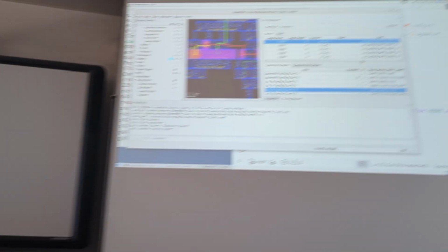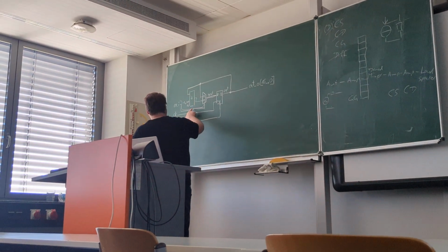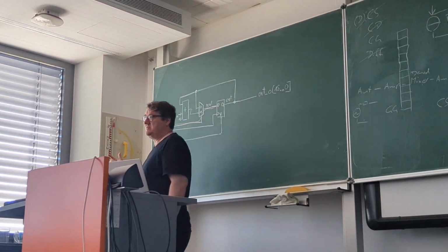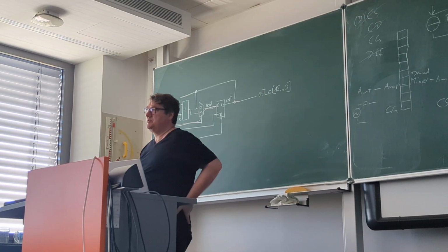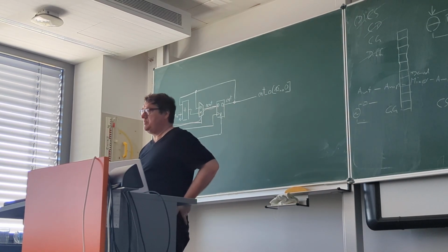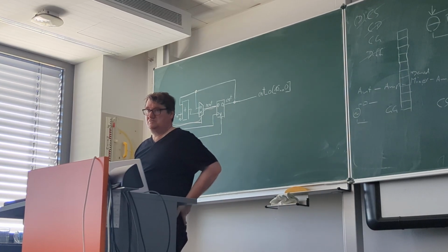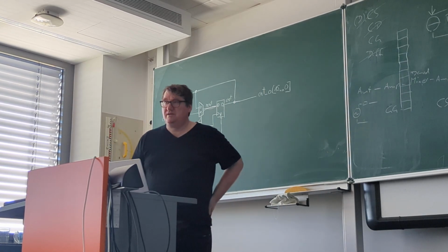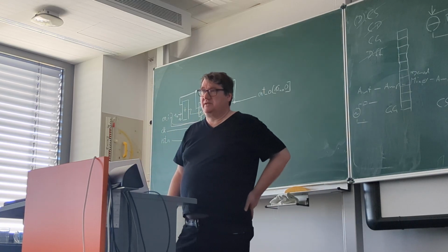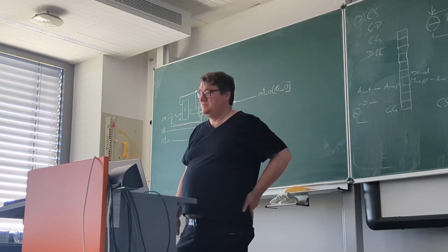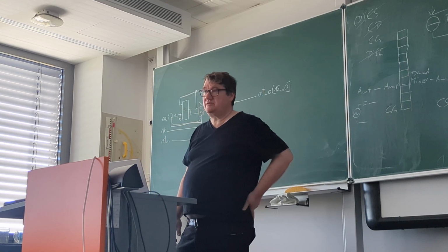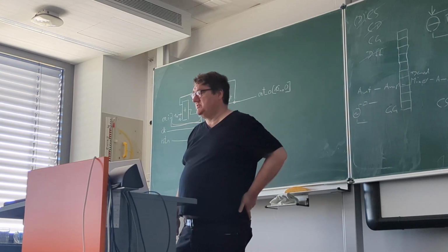So a flip-flop here, so that our 2 nanoseconds input delay, which comes just by definition, will be consumed by the first flip-flop, and then the remaining part is the internal logic. How do we change the VHDL code to get rid of that?